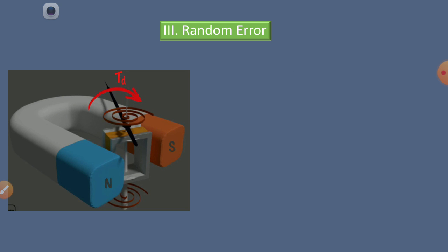Now you can see that in the case of moving coil instruments, here we are using the horseshoe magnet. Horseshoe magnet, a permanent magnet. As we know, the magnet power may change due to aging. Initially the permanent magnet has good intensity, strength. After using some years, what will happen? Due to the temperature effect, due to some mechanical defects, its magnetic field may be reduced. Then the permanent field may not be as much as at the start.